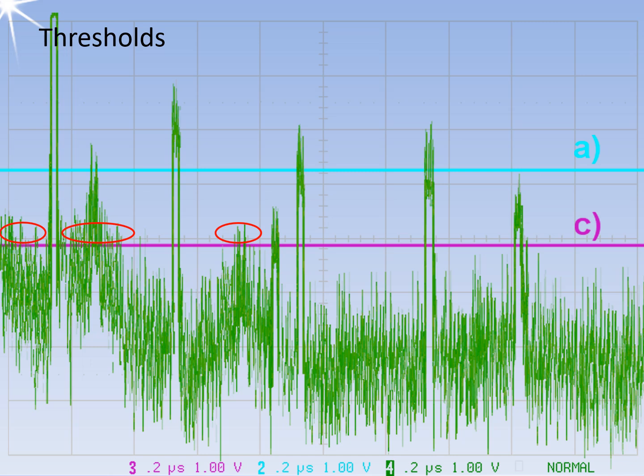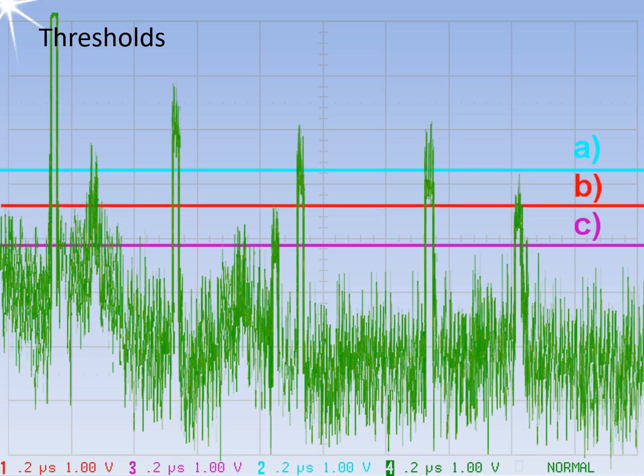If, however, the threshold is set too low, all 6 targets will be displayed correctly, but they would be difficult to see at close range due to the large number of disturbances and noise. All these disturbances are then false alarms. In this image, this would result in a false alarm rate of about 25%. However, in radar, a significantly lower false alarm rate would be desired, with accepted values around 10 to the power of -6. An optimal threshold is somewhere in between.